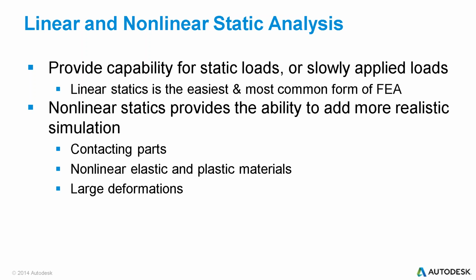If you look at the cross-section of an I-beam, for example, depending on the size of that I-beam, if it's deflecting a fraction of an inch, that may not be a very large deflection. If it's deflecting multiple inches, okay, yeah, we're getting into a nonlinear analysis type that would need to be ran. But it also goes down to material thickness itself. If you're working with sheet metal components, for example, you get a lot of nonlinear behavior in a sheet metal component just because of the cross-sectional wall thickness of that component.